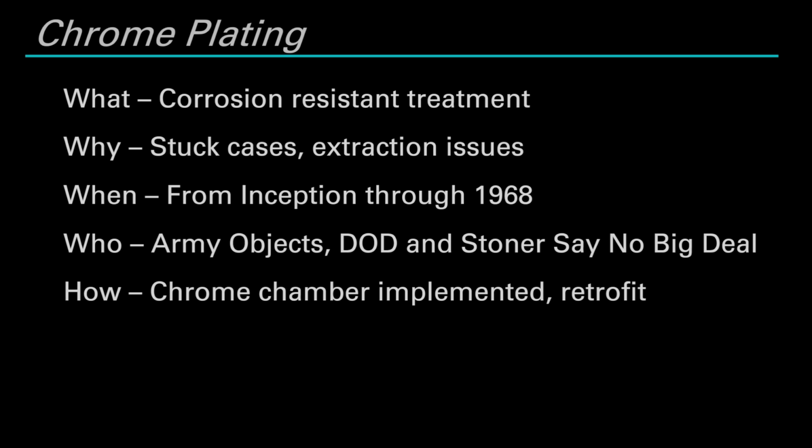So, a firefight that lasts longer than a day, so you don't have time to get the corrosive salts out if you're using corrosive ammunition, or get the rain out of the gun if you're in a particularly humid environment. The chrome chamber gives you the ability to not have to be extremely attentive to detail about keeping your rifle completely spotless. That's the advantage of a chrome-lined chamber and a chrome-lined bore.